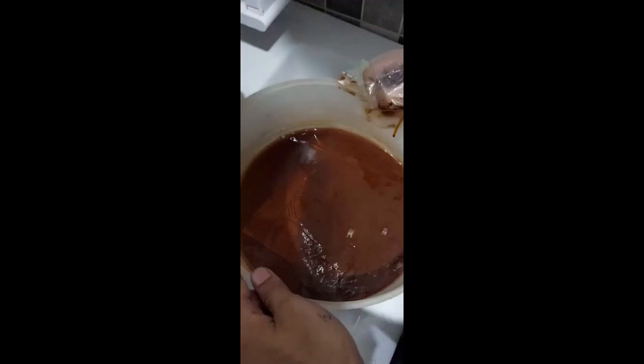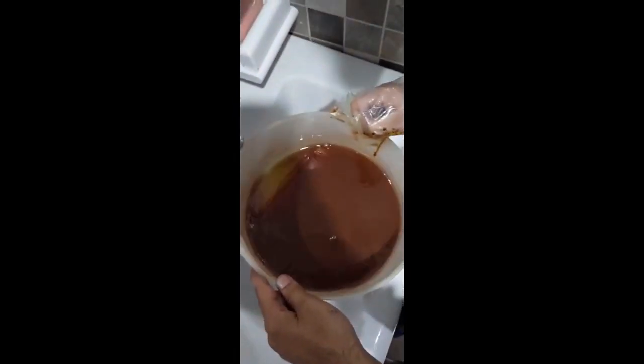When the design is prominent on the PCB board, the next step is etching. In etching, we are using ferric chloride solution, and we place the PCB board in that solution and leave it for almost 20 to 30 minutes, so that all the copper other than this path is removed from the PCB board, and we are left with the path that we have designed on the PCB.